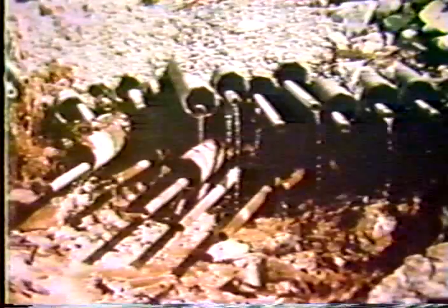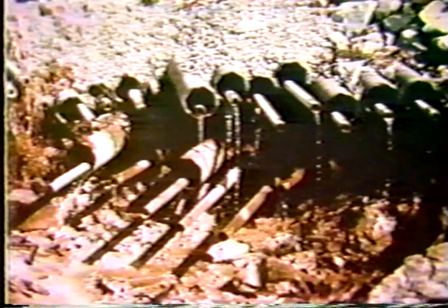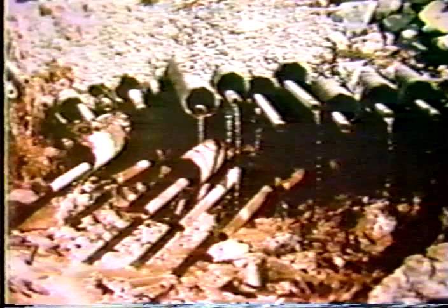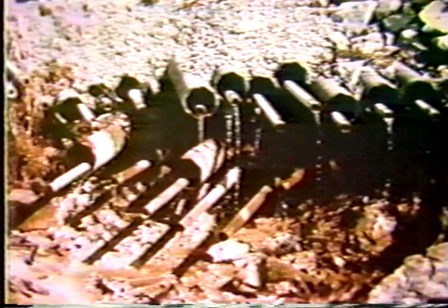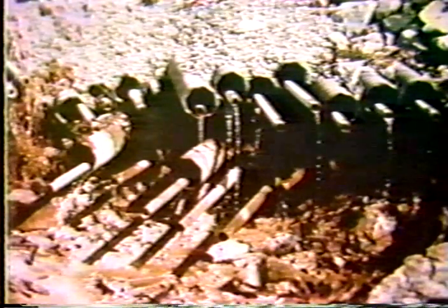Generally in the installation of horizontal drains, as I showed in the previous diagram, we're installing them in the lower portion of the slope or below the toe of the slope in the natural ground. Generally the patterns of installation are in rows and fan shape. And this is the installation showing where they've installed several rows of horizontal drains. Here's another close-up of installing in a fan pattern. Visualize in that particular diagram the drains and the casing running in all directions.